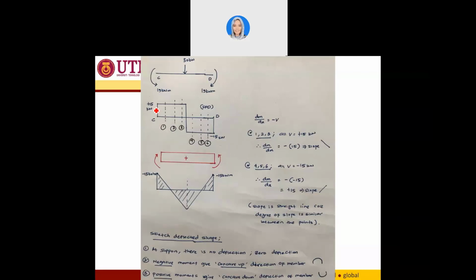So I have here, since the direction at point C is the opposite direction, if it is clockwise, it is positive here, but this one is counterclockwise, so I will have -15. This one is also a value of 15, and the direction also is the opposite direction. This one is supposed to be counterclockwise, but this is a clockwise direction. So again, I have a negative, so this is why -15. So at this point, I have 2 points here, -15 kilonewton meter and -15 kilonewton meter.